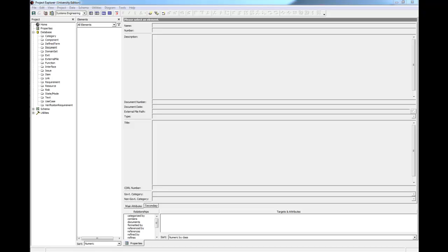Start with a blank project open. If you aren't sure how to do that, then go back and review Part 3 of this series. We will start by capturing the relevant information from the source document in Core. Core's element extractor is an easy way to transfer text from a document into a Core database. In the Project Explorer, click the element extractor icon.